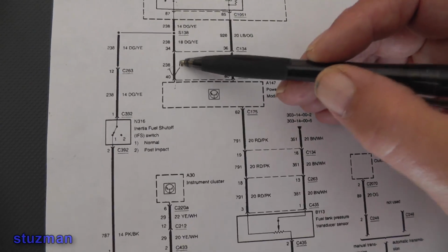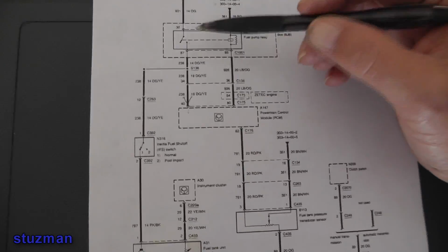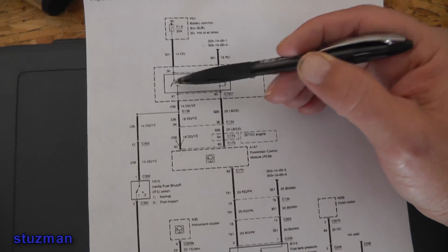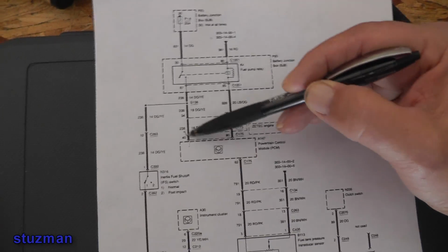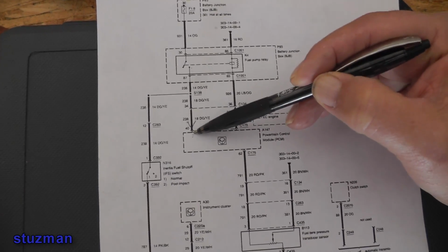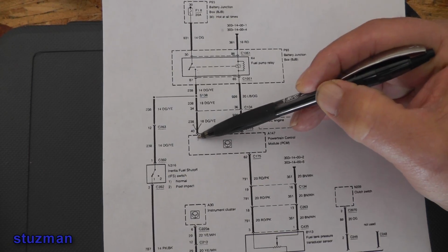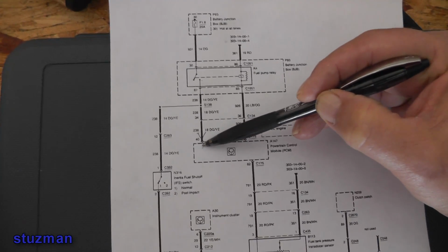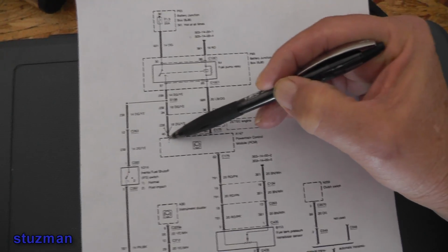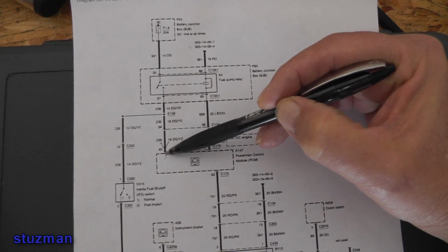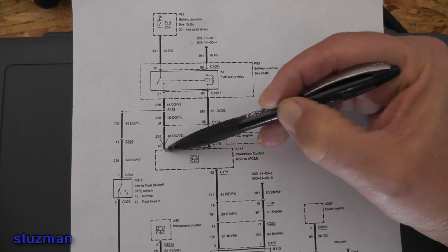Or on the other hand, when you turn the switch and the engine is running, we know the relay's contact is closed, and now it's going to be putting B plus up to this input. And at this point, it knows everything is good. But what if there wasn't B plus here? Then again, it knows there's an issue. So again, you can get a code.